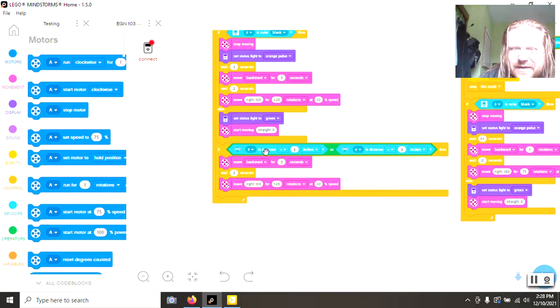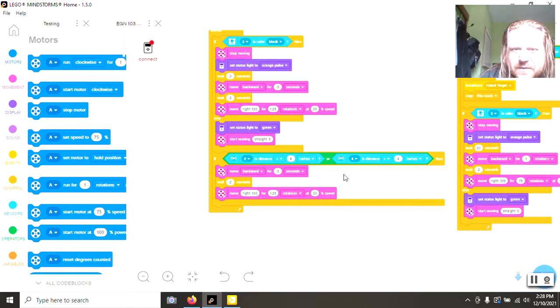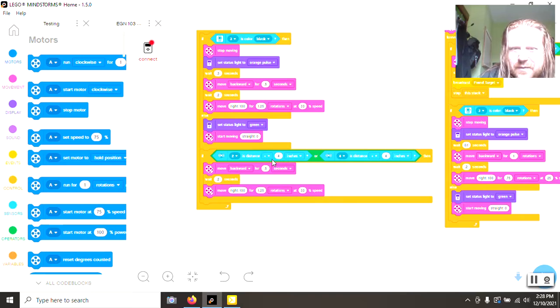Now I have these ultrasonic sensors. They're going to react in this loop to any obstacles that they detect. And here it's set at 4 inches. Now you'll notice you can adjust these to equal to, greater than, or less than. And let me suggest not using the equal to, because that might work 1 out of 30 times. The sensors go out of range constantly, and so trust me, use the greater than or less thans.